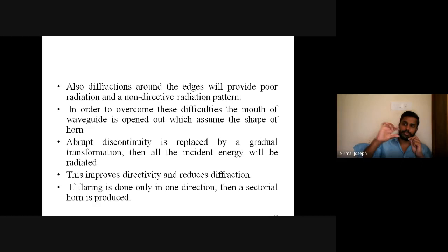So what the wave will feel whenever it comes to the edge is that it is gradually opening up. The wave will feel that the waveguide is continuing, and at a particular point it can escape to the space. That particular shape is referred to as the horn shape. I will show the pictures and all.